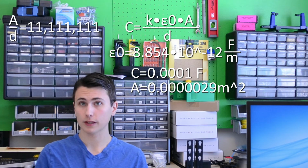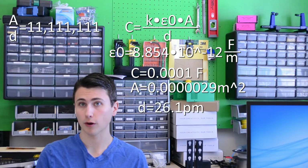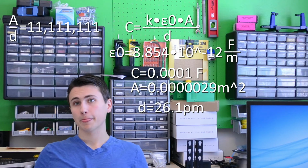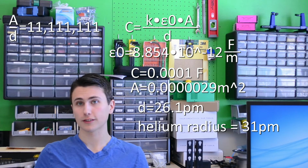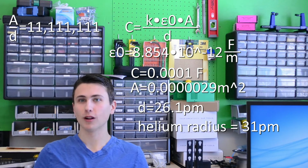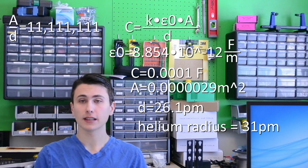Assuming that the assumptions we've made so far are valid, the two plates inside this part would need to be no more than 26.1 picometers apart. For reference, a helium atom has an atomic radius of 31 picometers. That's right, our plates would need to be closer together than the smallest atom on the periodic table. So what does this tell us? Well, this tells us that the capacitor I'm looking at the datasheet for is not a parallel plate capacitor in free space.